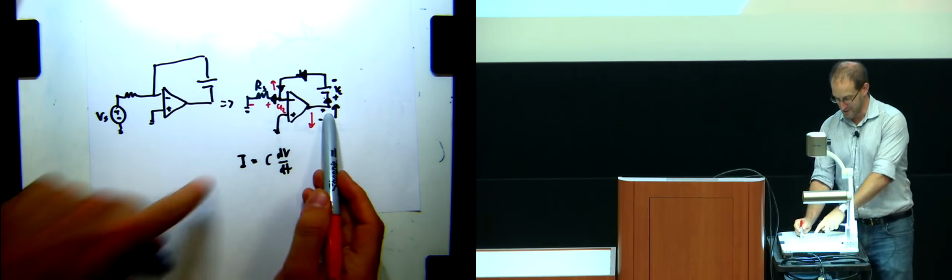So because of that, yes, other than what was brought up before about the limited supply range of the op amp itself, technically whatever this voltage is, as long as it's not outside of the range of the op amp, you're still in negative feedback. Because it's all about the current being created by the change in voltage at the output. It's a good question, though. Other questions? Yes?